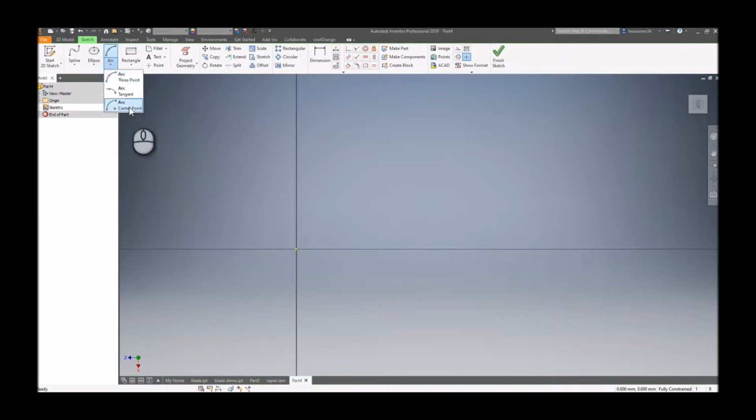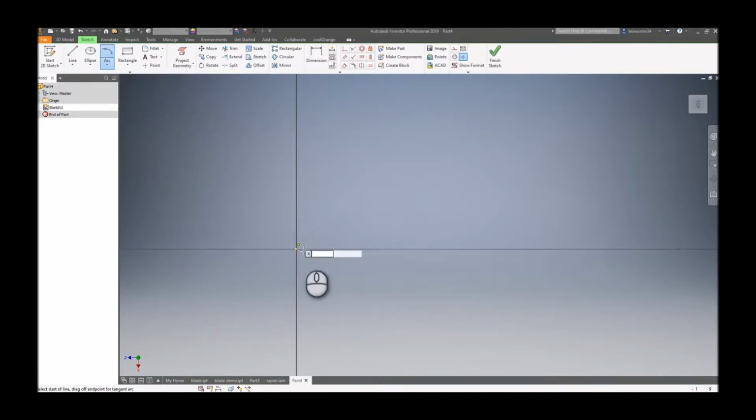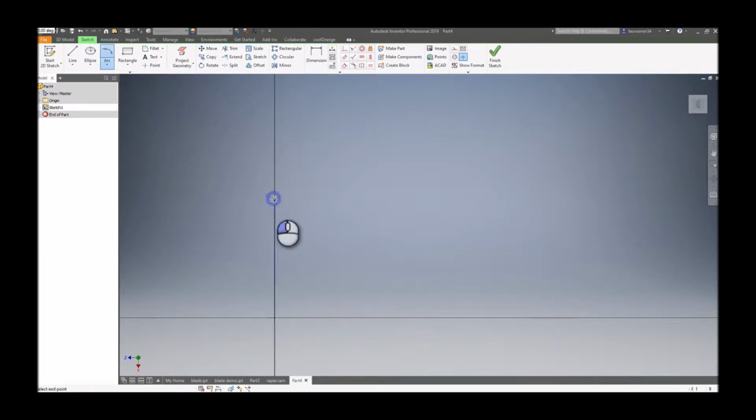Second type, it's called a tangent, which means if you have an already defined line, so let's just take this and okay. Take a tangent, it'll automatically make it so that part has already got a tangent constraint on it, so it'll always be tangent. And it gets pretty wacky. It's also good if you want to make like candy canes, hooks, etc. And then you've also got the center point, which is similar.